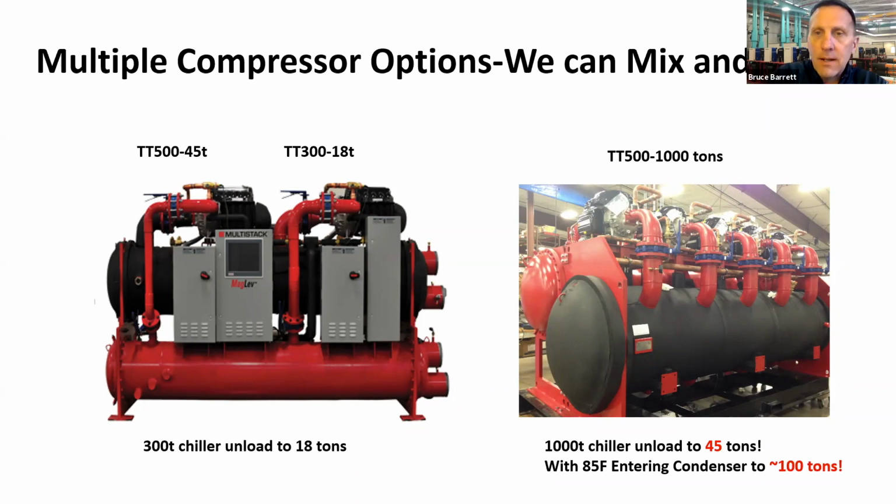There are safeties on the chiller, I should say control safeties, not on our chiller. We actually look at suction pressure, discharge pressure. Our chiller will say, I can't start, your condenser water is too cold. We usually have a controls directive to state what your minimum tower water temperature is, and then enable the chiller once that temperature gets there. But yes, you can run that through the chiller.